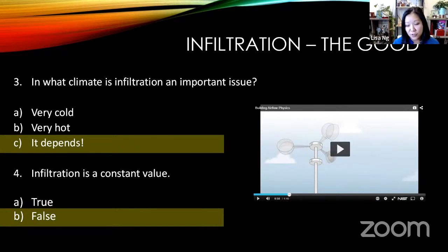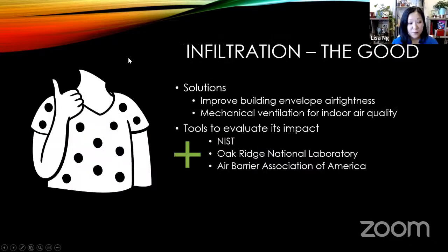And then number 4, infiltration is not a constant value, which I'm so glad to see that people understand. It's definitely affected by weather, HVAC operation, and the video, like I said, will show more of that in an animated form. So thank you all for the participation. Hopefully you can come up with some questions for discussion later. So infiltration, the good about it is that, like I said, many of you know more about infiltration than maybe you thought you did. You understand the concepts, and that's great. So what we can do about infiltration is we can reduce it, because there are better and better technologies to improve building envelope air tightness.